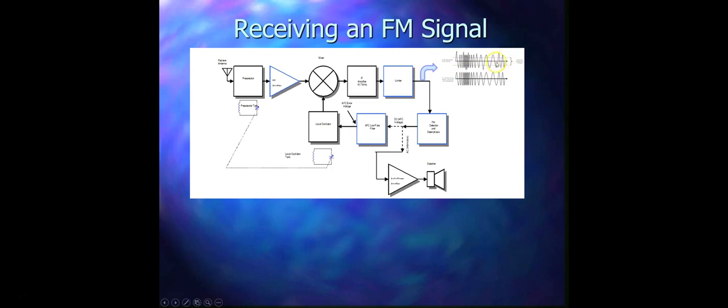Like in the AM receiver, it is quite affected by these noises, but an FM signal is not that much affected by the noises. That's why we use a limiter here, and with the help of the limiter it flattens the top and the bottom of the modulated wave. So you see here, after using the limiter, the waveform will look like this. It flattens the top and bottom of the detected output voltage waveform, and it eliminates most of the noise but preserves the information. That is why FM receivers are free from static interference, and the detector sees only the frequency change in the modulated waveform. Hence we can say that the FM receiver can safely ignore all amplitude changes without losing any information with the help of this limiter.